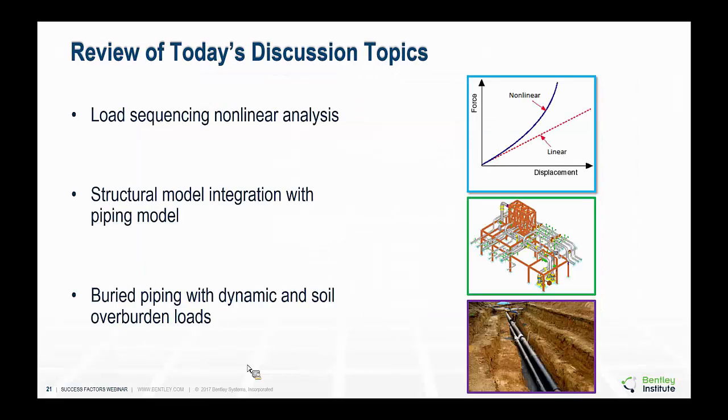And to review what we have discussed today, we've talked about the load sequencing nonlinear analysis that AutoPIPE has that meets the ASME code philosophy. We've got our structural model integration that AutoPIPE has with STAAD and SACS, and the buried piping module that AutoPIPE has that provides many great capabilities.